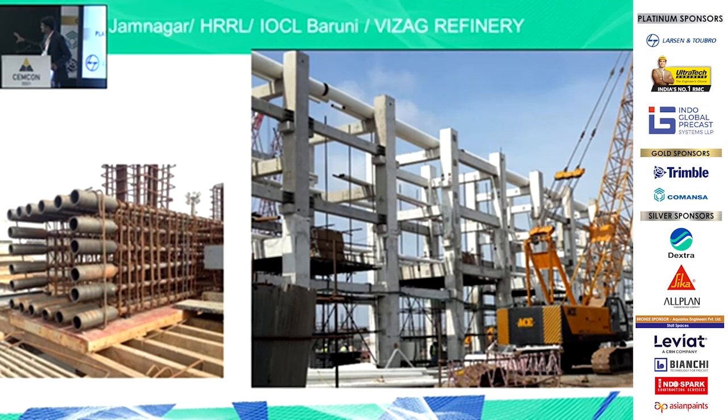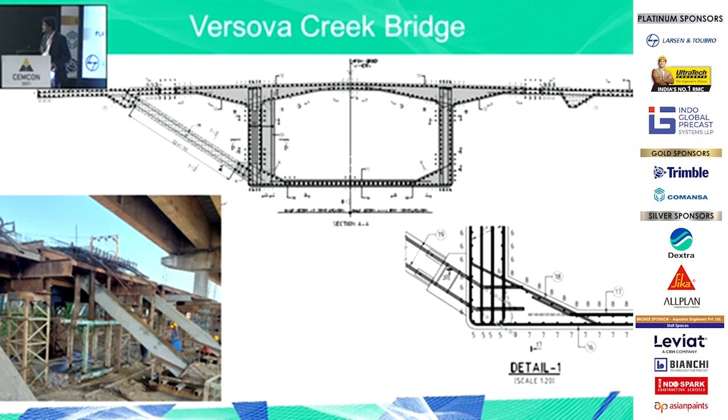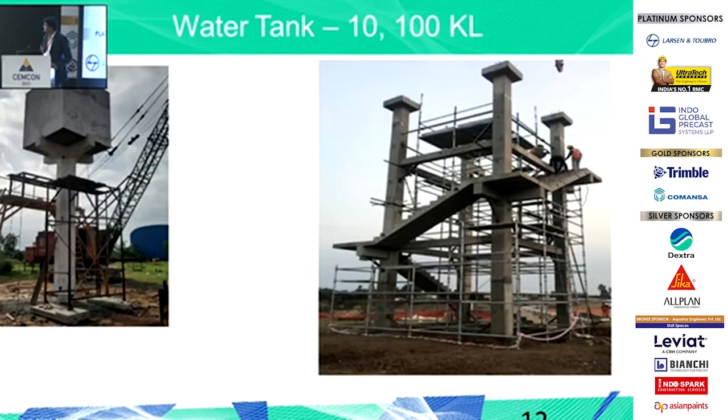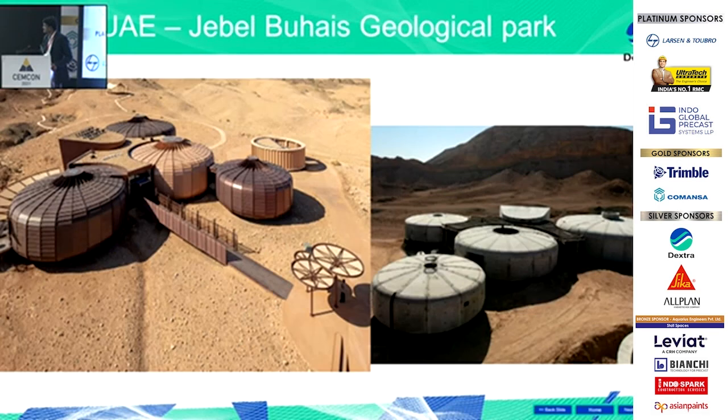And this is how the frames look. Being a heavy precast element, weighing up to 50 or 60 odd tons, this becomes an effective solution. Recently, we have entered infrastructure projects, which is for bridges. The struts which come out from the segment are connected with the grouted coupler. This is one example. And when you talk about applications, we are also entering water tanks. Water tanks are being done in precast, and we have done a few mock-ups for water tanks with grouted couplers.